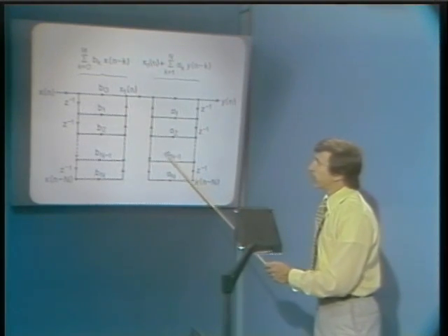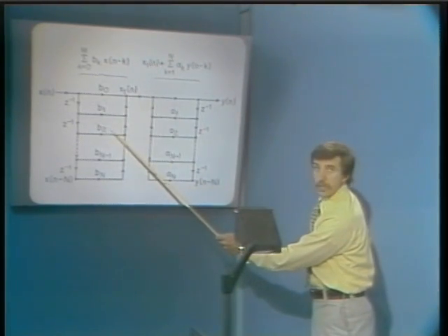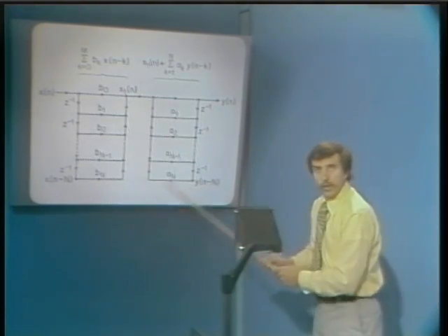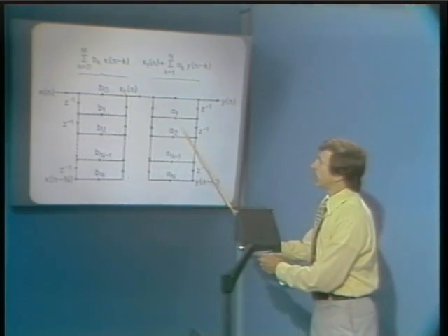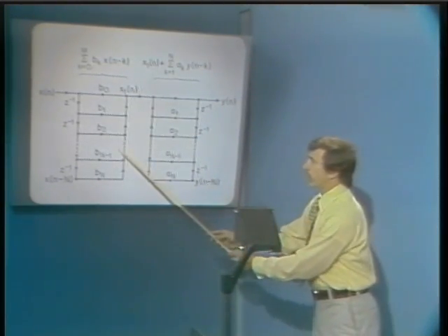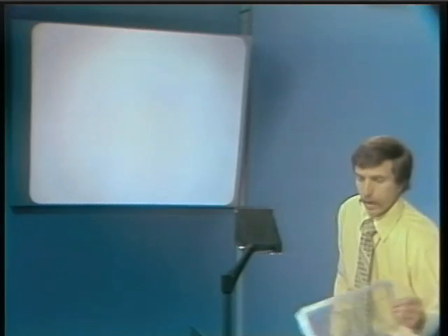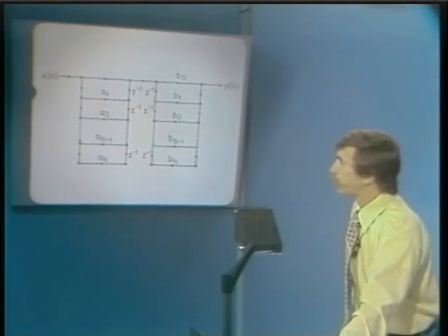That implementation in particular, whereas this one has the zeros first, followed by the poles, interchanging the order of those two will result in the poles implemented first, followed by the zeros, and the system that results is what I've indicated on this next view graph.